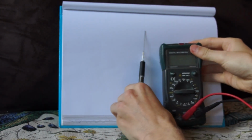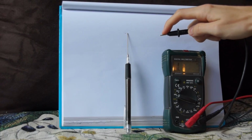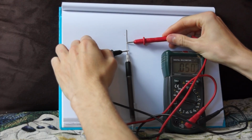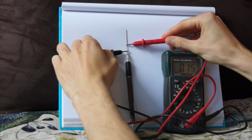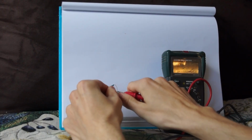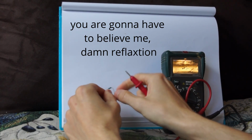We can measure resistance using a multimeter. Measuring across this pencil gives us a value of about 22 ohms, although it's hard to say because the contact points of the multimeter change the value a lot. If we halve the size of our pencil, it should halve the resistive value. This seems to be about 10 ohms, so that should be correct. If we measure the resistance across this little resistor here, we see that it's about 900 ohms.